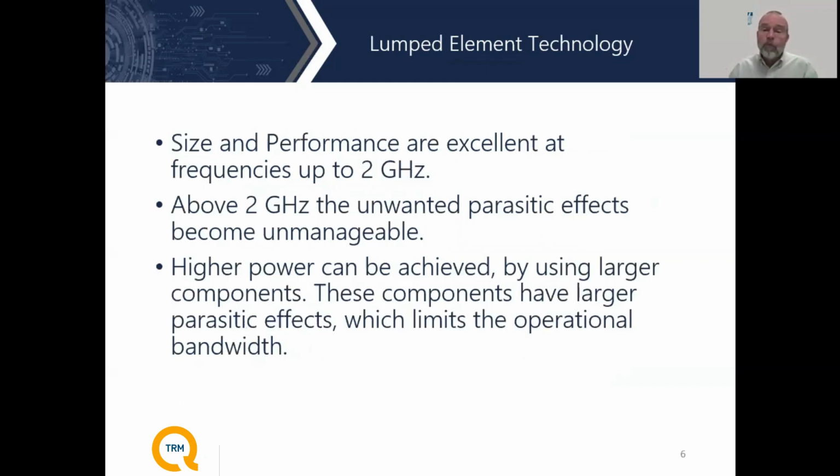So the upper limit is really typically around 2 gigahertz. Sometimes we go up to about 3 gigahertz depending on the individual circuit. But really, what happens there is that the interwire capacitances and the stray reactances of the transformers really start to become unmanageable. And so we do get a high frequency cutoff of these devices somewhere in the 2 to 3 gigahertz range.